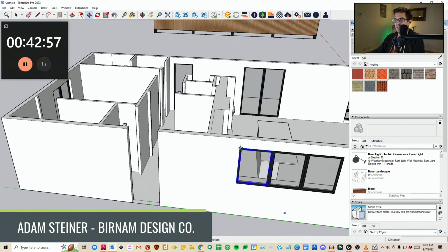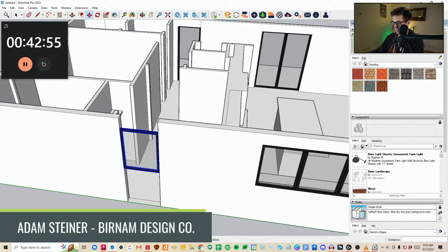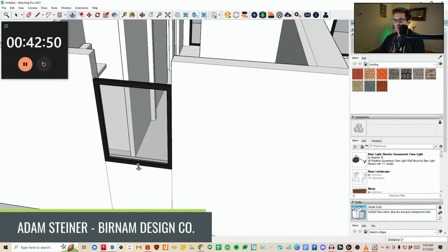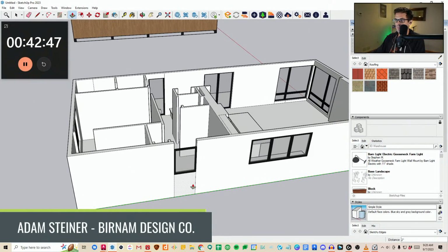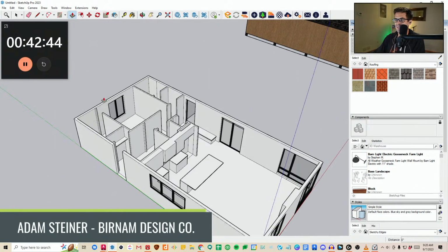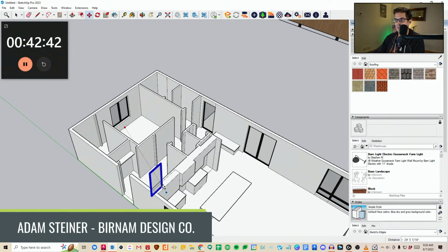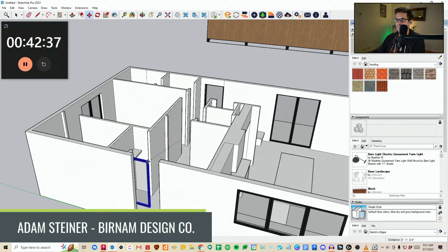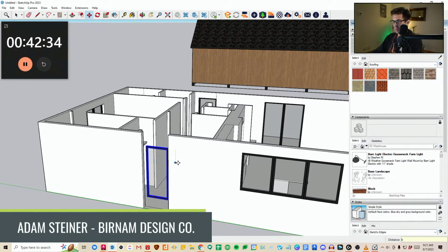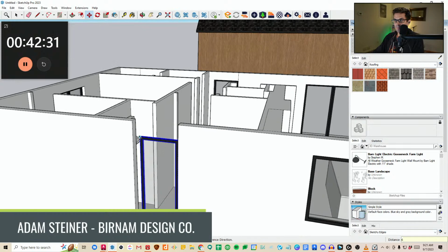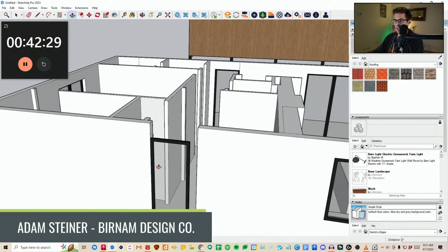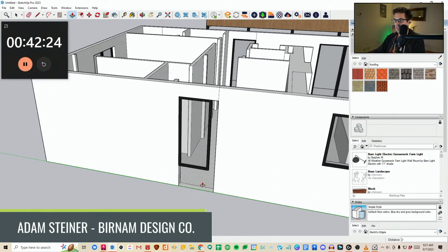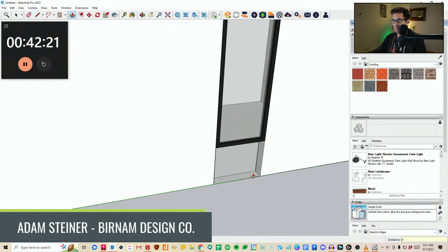Actually, let's show one of these so that we can do a desk up to it if need be. Although that won't meet egress, will it? It's not close enough to the floor. All right, let's go back to plan A. Do this bad boy. I'm showing all the top of windows at 8 feet. 8-foot head height there, which is pretty common.